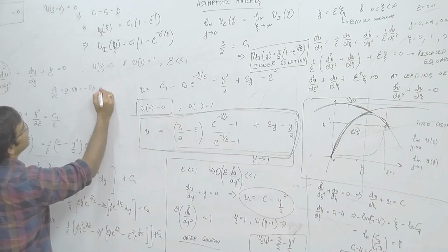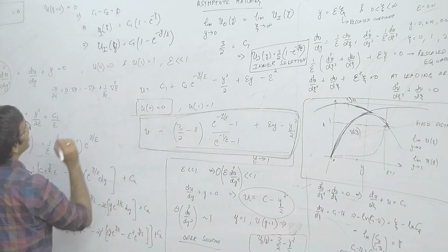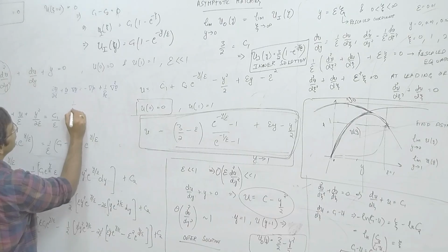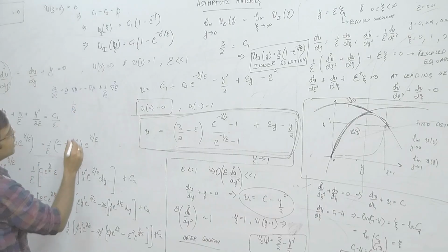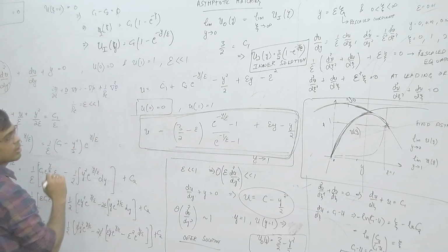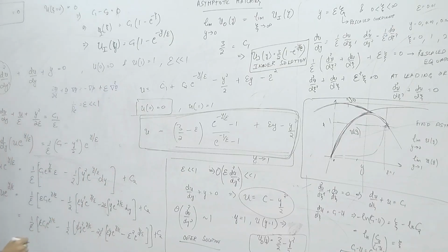This is the dimensionless Navier-Stokes equation. And look at it in the limit of large Reynolds number. So let us say when Reynolds number is large, this 1 by Re is some epsilon which is much less than 1. Okay. So I'm going to replace this 1 by Re with epsilon.